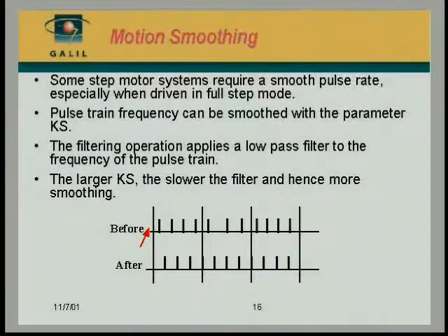You may have some pulses at some rate, and all of a sudden a big gap, and some pulses, and so on. When those pulses are applied to an indexer, you're basically telling the stepper, move fast, slow down, fast, and so on. And as we mentioned, steppers don't like to change direction or change speed abruptly because they're underdamped. This may cause overshoot and loss of synchronization altogether.